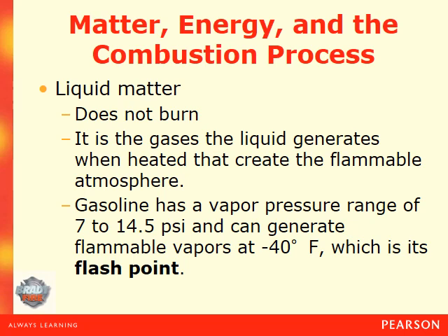Liquid matter does not burn, just like a solid matter does not burn. It is when that matter is turned into that gaseous state that it will actually create that flammable atmosphere. Gasoline has a vapor pressure range of 7 to 14.5 psi and can generate flammable vapors at as low as -4 degrees Fahrenheit, which is its flash point.